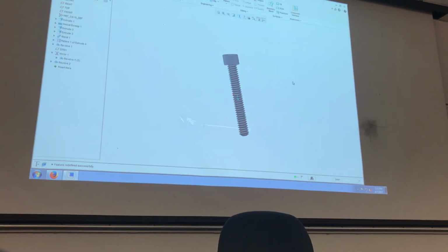If you were designing features and parts that are going to go together, okay, which we'll get into in the introduction to the design. Say you're doing a shaft and a hole connection fitting. Okay, first thing you have to do is determine what kind of fit do you want. Do you want it to become a permanent fit? Do you want to be able to put it in, have a set screw that holds it in place? Do you want to have a slight force to it? You've got to determine all that as the design engineer. Okay, so once you figure that out, you go into what's called machinery handbook and look up the different types of fits.